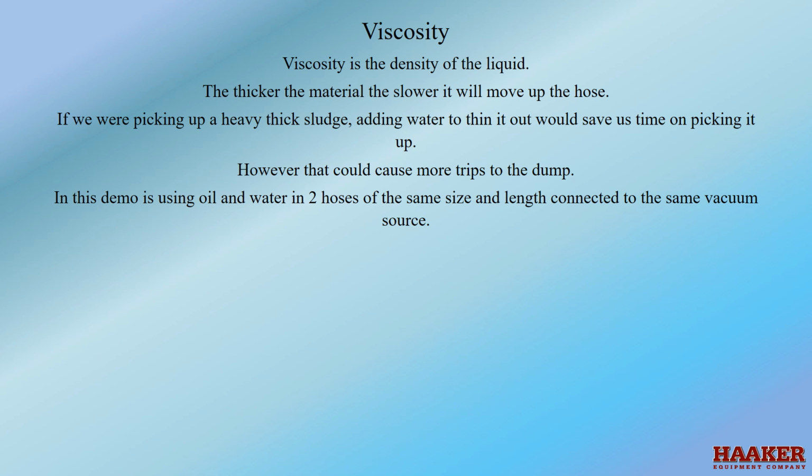Viscosity. Viscosity is the thickness of a liquid. The thicker the material, the slower it will move up the hose. If we were picking up heavy, thick sludge or grease, adding water to thin it out would save us time on picking it up. However, that could cause more trips to the dump.